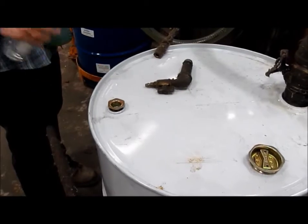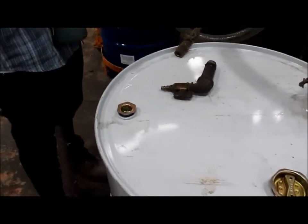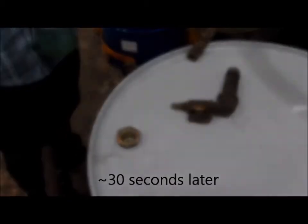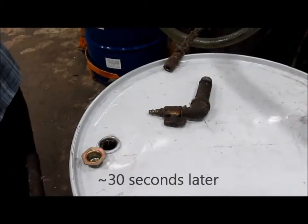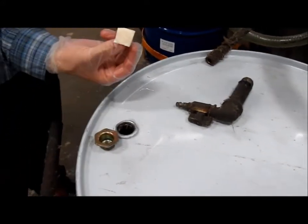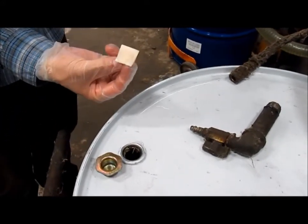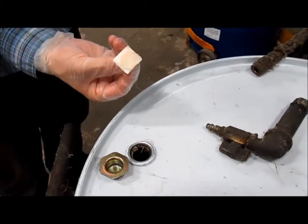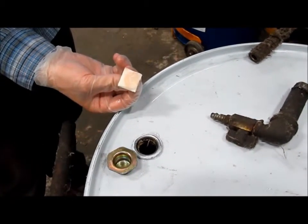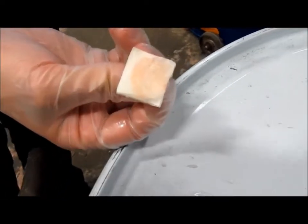Looking for isocyanate contamination, we lightly spray the test surface with our developing solution near the opening of the drum. Wait approximately 30 seconds, and then wipe the surface with an aromatic isocyanate surface swipe. In this case, the color reaction started almost immediately due to a contamination on top of the drum as a result of the removal of the hose.